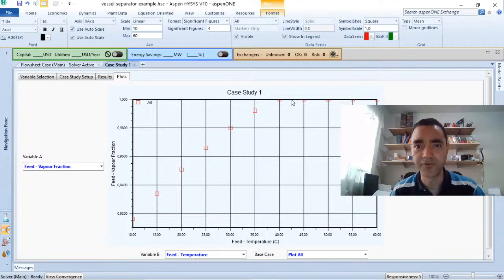Or we can define that instead of the alarm being 40 Celsius degree, it can be 45 Celsius degree, and so between 45 and 40, the operator has time to do some kind of verification or some kind of action to avoid the formation of condensate.